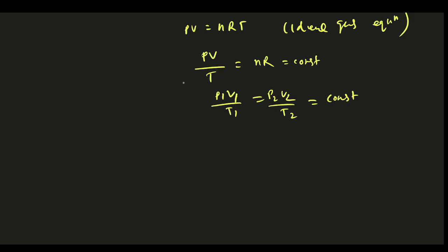So for the adiabatic process, we will not go the way we went for the reversible isothermal process. There we used the ideal gas formula, said PV equals nRT, and since T is constant, PV is constant, so we put P1V1 equals P2V2 in the work expression.